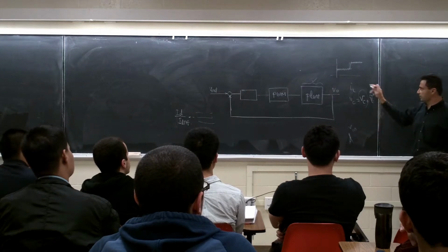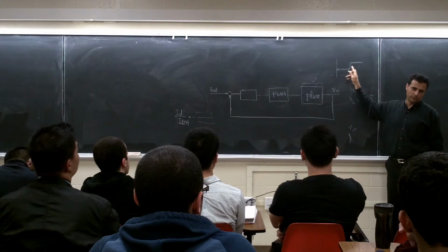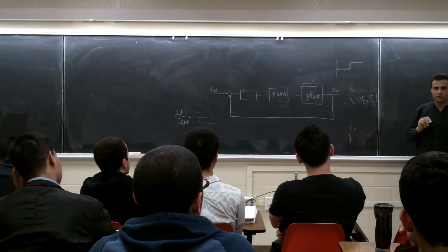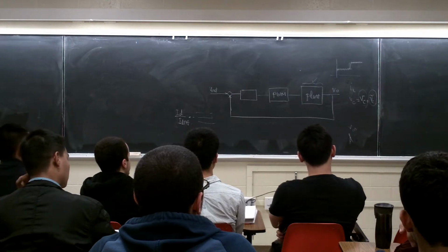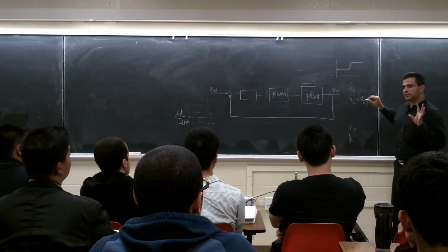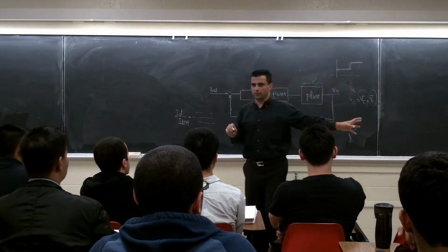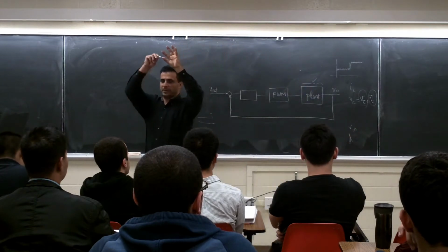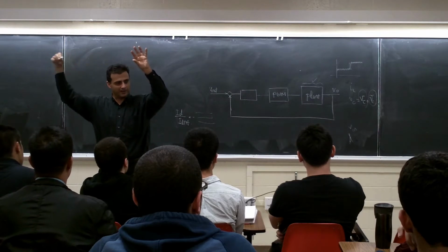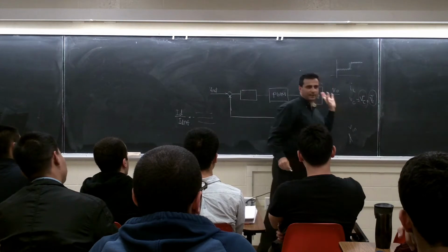And this VC tilde is the ripple on this one, or going around this one, right? So I want to get the equation based on this one, because usually we want to minimize the ripple. We want to make sure the control is good. So this is a DC operating point. We are going to go from here to this point, from 1 volt to 5 volt. But now I need to have control to control the ripple here, to keep the system at this point, right? So this VC, we're going to see how we're going to get the equation.